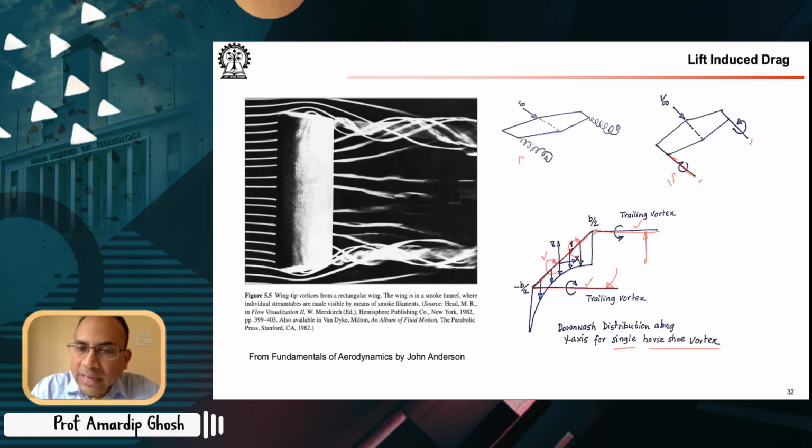So there is no pressure difference at the tip. So there is no lift, hence there is no circulation at the tip. So circulation decreases from a maximum at the root to zero at the tip. Remember we said that the product of vorticity and the cross section will remain constant. So if circulation is decreasing, that circulation is actually put into other horseshoe vortices.